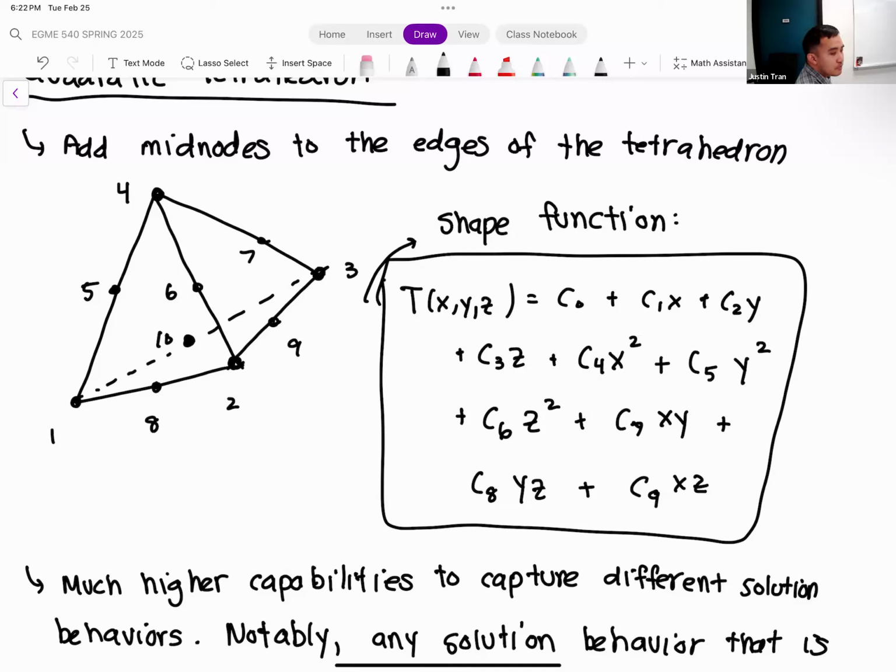You mentioned that skewed elements lead to less accurate results. It depends sometimes, and generally the expectation is that if you do have a lot of skewed elements, then that's not good for your solution. Because a lot of times, when you're computing derivative-based quantities and you have two nodes that are really close and one node that's really far, that's usually not good.